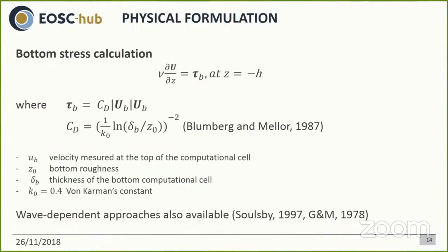For the bottom stress, the approach of Blumberg and Mellor is employed, where z0 corresponds to the roughness length, which can account for bed forms in sediment transport simulations. Wave-dependent approaches, such as those of Soulsby or Grant and Madsen, are also available.